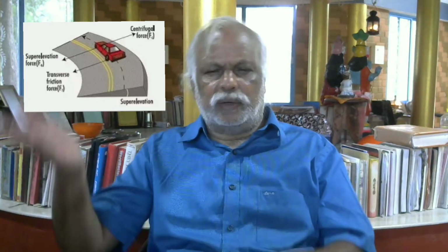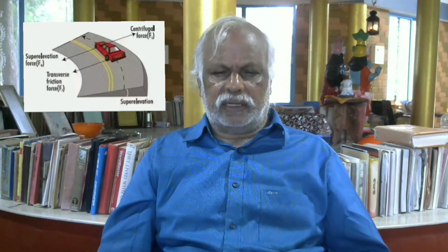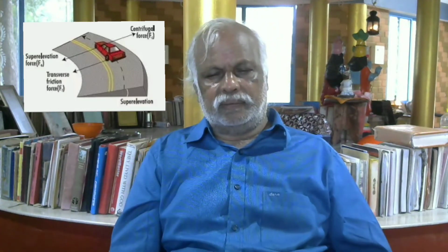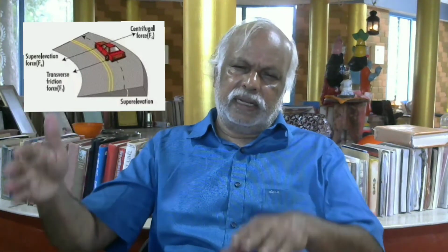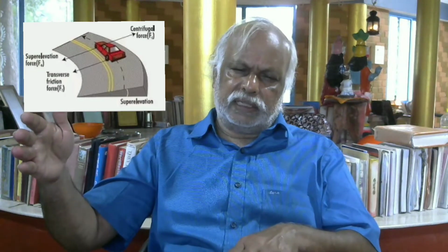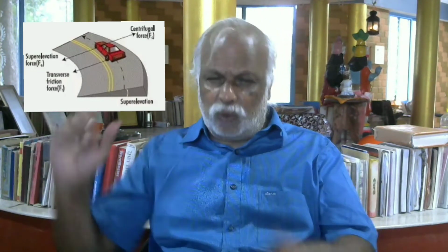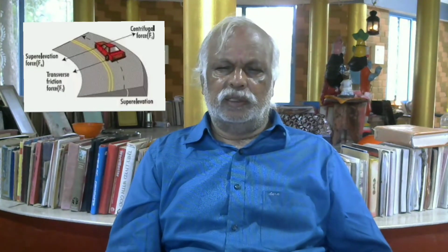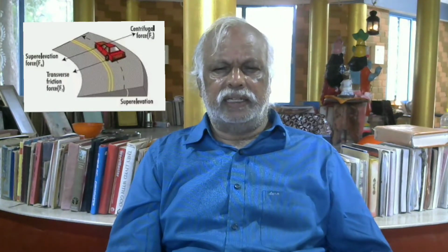This elevation will be mathematically fixed, there are equations for that, and the relative raising of the external part compared to the internal part only on curves is known as super elevation. Super elevation or cant, C-A-N-T, cant or super elevation.